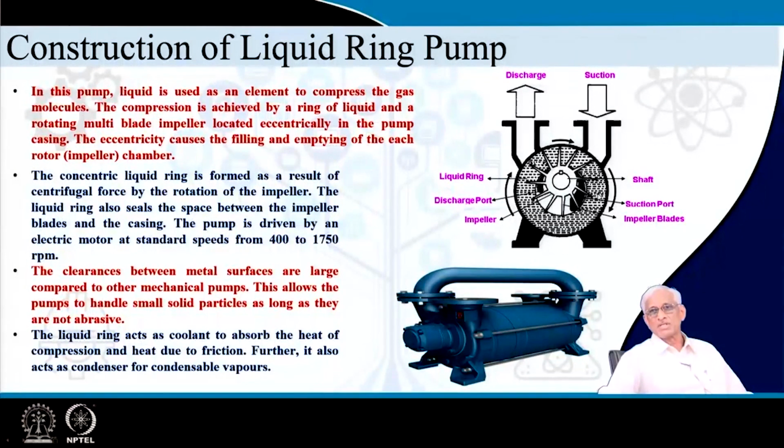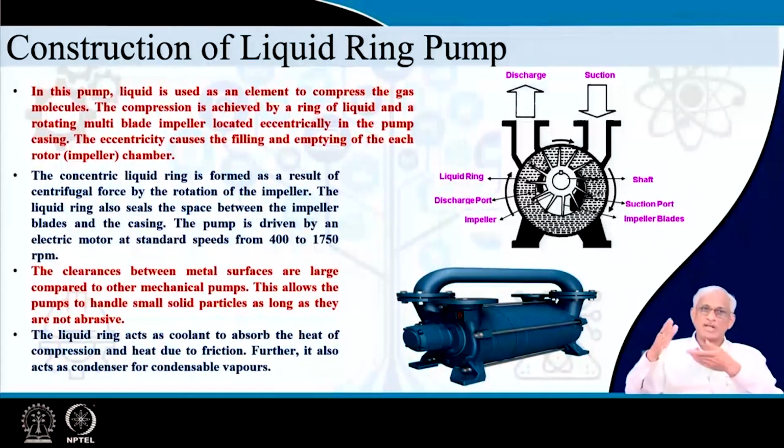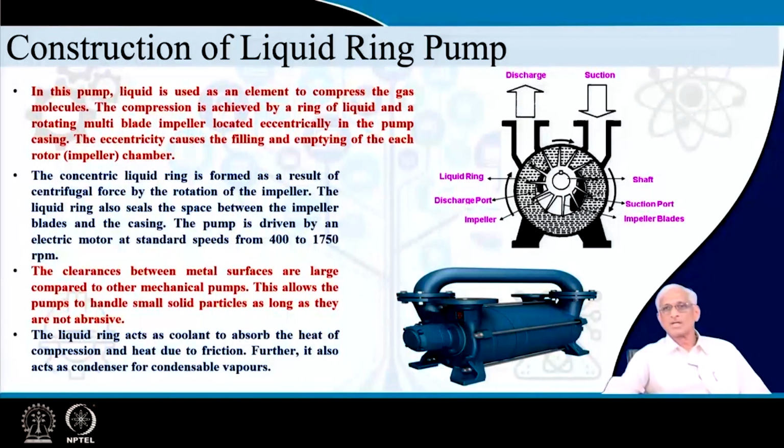And these black looking things are inlet and exhaust valves, which are coupled in this direction to that annular space, which is an increasing space or decreasing space. There will be inlet and outlet connected to the body. So, there will be suction inlet and there will be exhaust discharge.